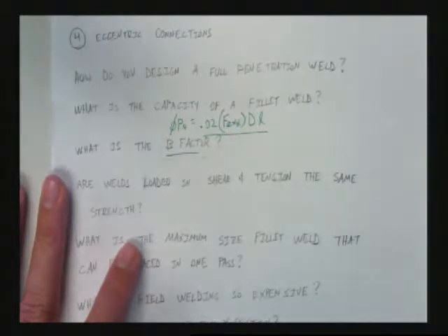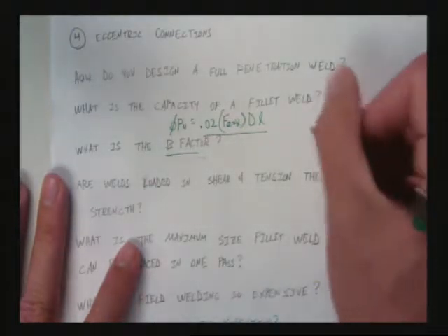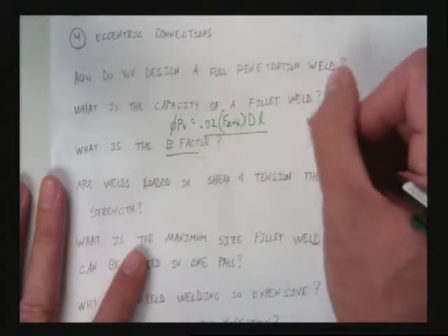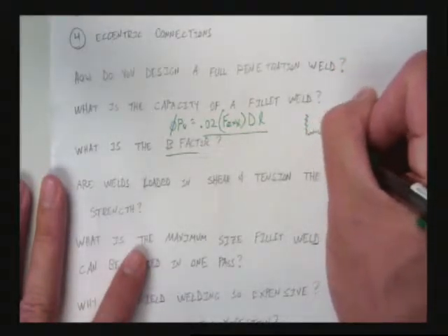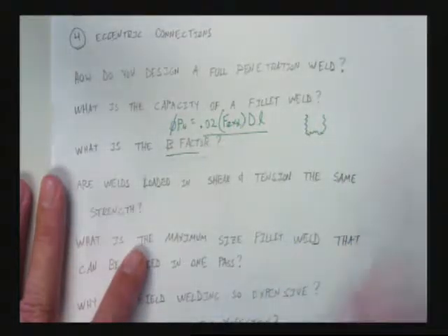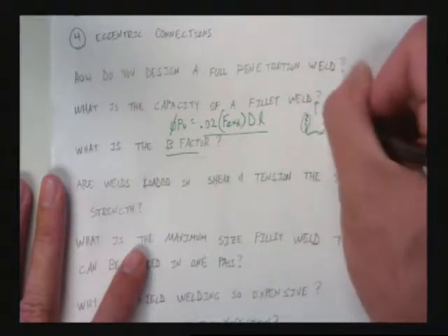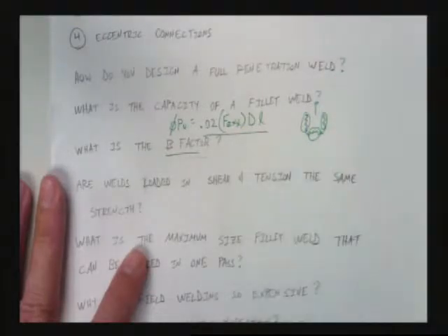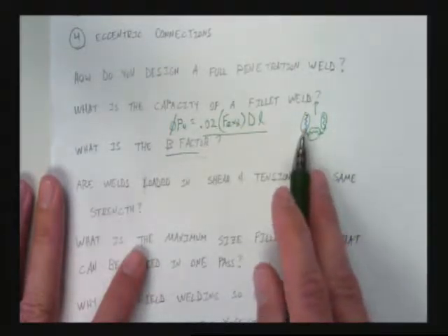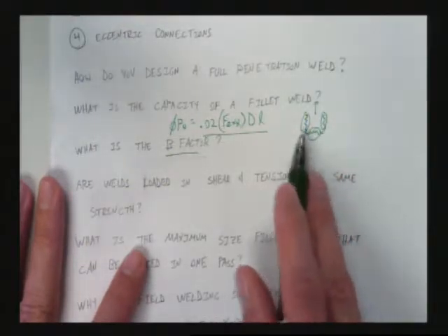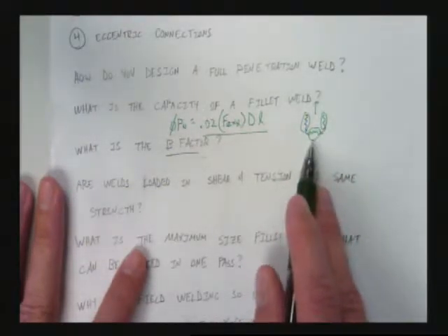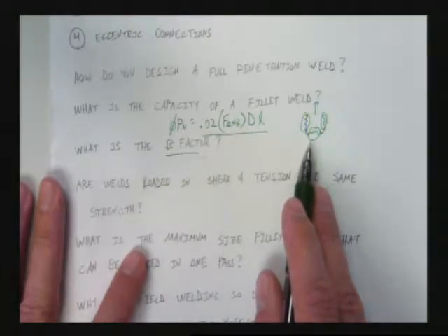Or an equation where it's either 0.85 RWL or 1.5 RWT. So that's a little bit different. That's when welds are loaded, when welds are like this and being loaded, right? Where you have welds simultaneously in tension, in shear and in tension, right? And that's where you take into account, you either use RWL plus RWT, basically the assumed shear capacity for everything, or you use 0.85 times the shear capacity plus, was it 1.5 times the tension capacity? Yeah? Times RWT, tension capacity, plus 0.85 times RWL.